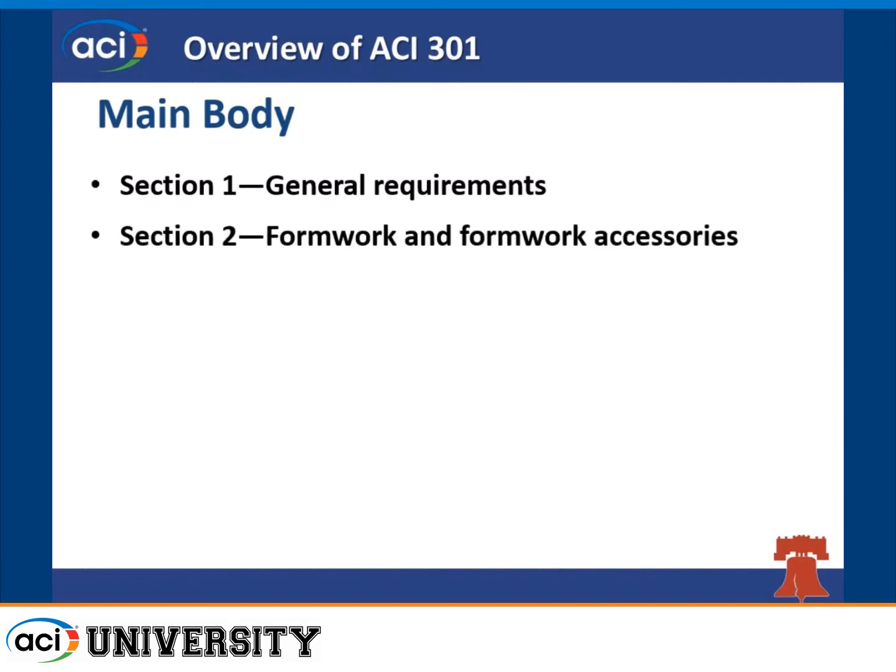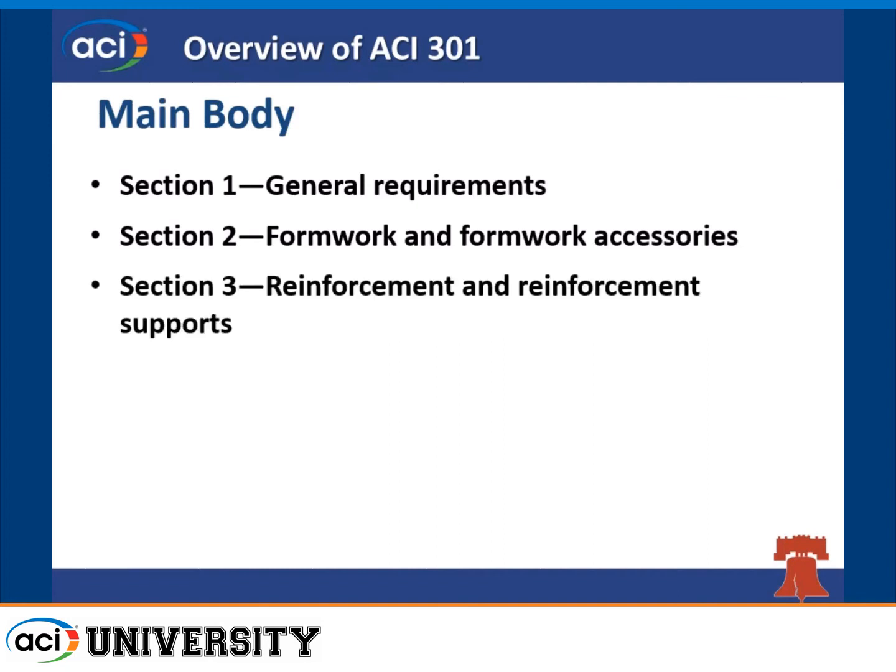And then section 2 is our formwork and accessories. Section 3 is reinforcement and reinforcement supports. So we get into a lot on making sure that we have not only just the correct rebar, but also the certification for it and the tolerances. Section 4 is on our concrete mixtures. It's not necessarily doing the design for you, but telling you what materials to use. And then once the specifier has deemed the strength, it tells you if there's any that are restricted in the special areas.